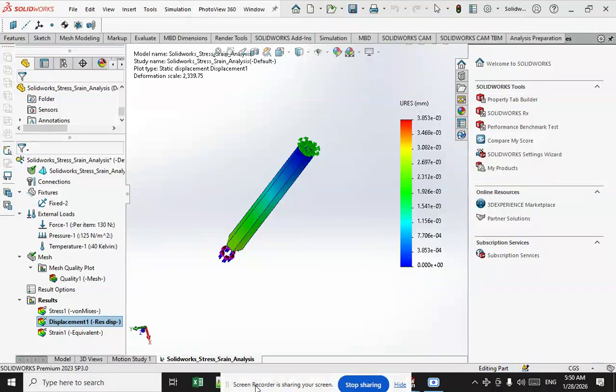From the measurement of strain on a surface in multiple directions, the stress state that developed in the part can be calculated. Neutron diffraction is a technique that can be used to determine the subsurface strain in a part. The next one is the photoelastic method, which relies on the fact that some materials exhibit birefringence on the application of stress, and the magnitude of the refractive indices at each point in the material is directly related to the state of stress at that point.